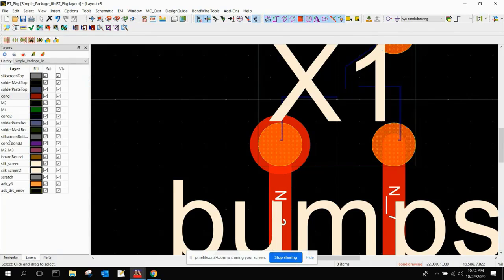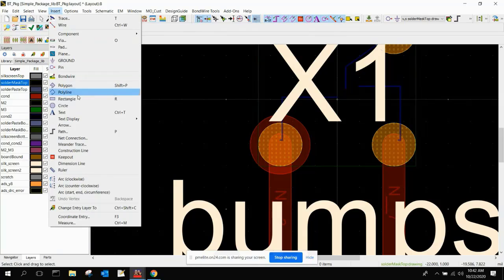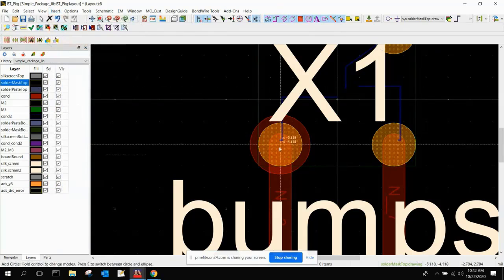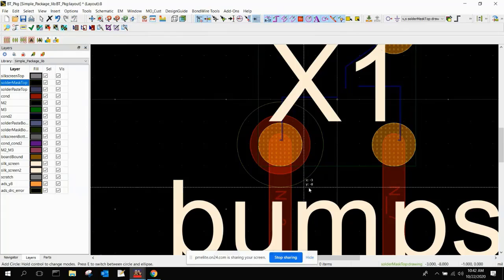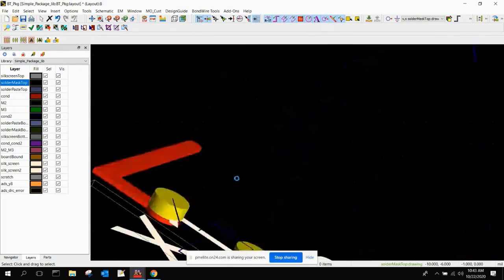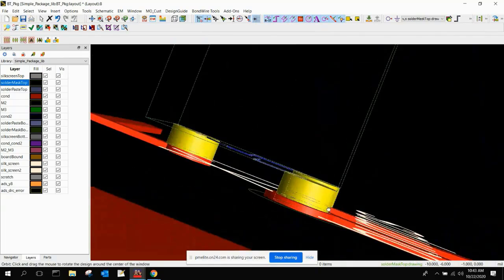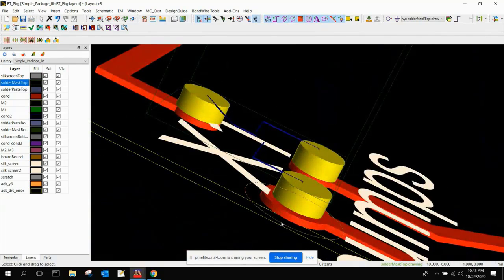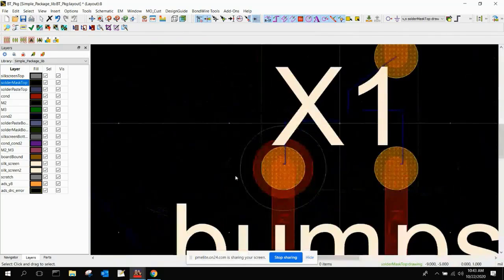And the other thing with some of these technologies, in this case, I've got a solder mask layer. So there's actually, on this package, an isolation protect layer on top. And technically, what I need to do is remove that isolation layer to place the chip so that there's metal on metal contact. So I'm really exposing the metal of my package here so that I can land the chip, so that I can solder the chip to the metal on the package. So I need to add 2 layers to this. Well, really, I need to add a bigger landing pad and a solder mask layer for this to work.